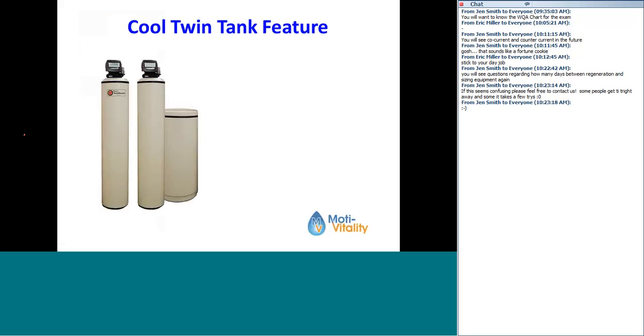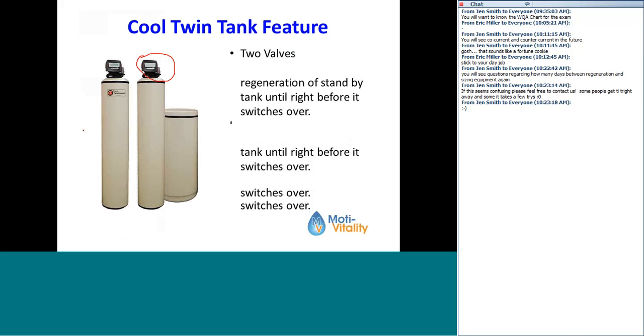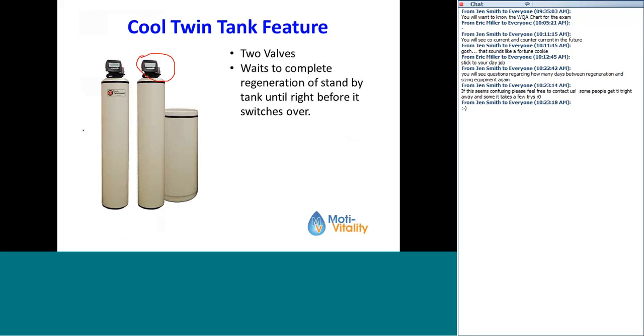One of the clients that we have has a cool feature on their system. It's kind of a unique feature. It's a twin tank system, but you have a valve on each tank, and this valve here is a secondary valve, and basically what it does is it waits to complete the regeneration of the standby tank until right before it switches over.